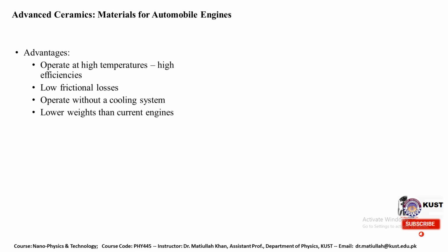We have advanced ceramics that are basically used for automobiles, and advanced ceramics have high efficiency because they reduce the wear. They have very high wear resistance and are stable at very high temperatures. Such ceramics are used in the interior part of engines, because even if the engine is operating at very high temperature, the ceramic layer is stable, especially when we are using thermal barrier coating that gives heat insulation to the engine, as well as being stable at very high temperature.